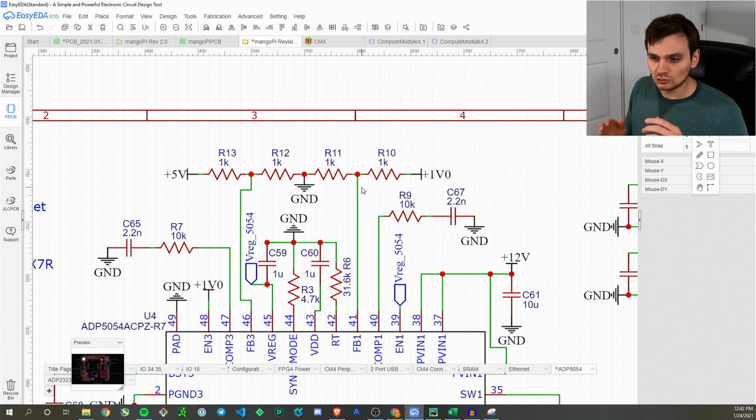So it will continue to adjust the duty cycle of the output, which is basically raising or lowering the voltage on the output, until this pin is reading 0.8 volts. And then it will make sure that it'll stay there no matter what the load is, up to the max supply that it can output, which in the case of channel 1 is 6 amps.